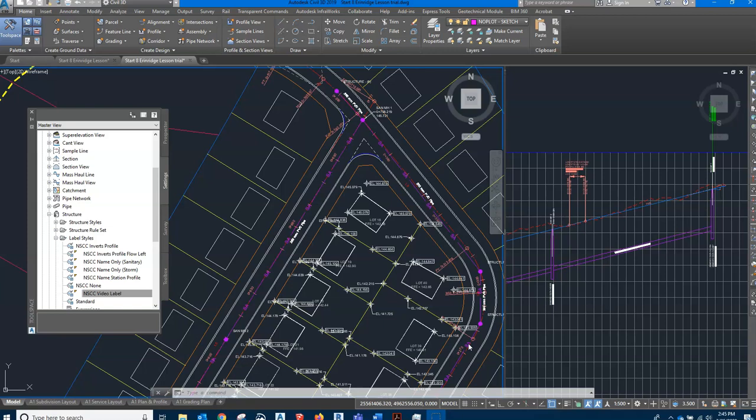With our Civil 3D tools, we can actually enter rules for our networks, and automatically, when we are drawing our three-dimensional layouts, the software will put it in with the correct cover and the correct slope. Making it a lot more automated for the designer.